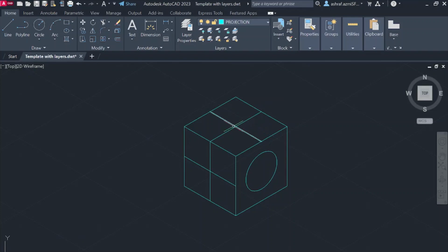Once you have this center base point for circle, you can draw the circle, ellipse. Circle in a normal view, whereas ellipse for isometric drawing. Then click isocircle. The diameter is 3.